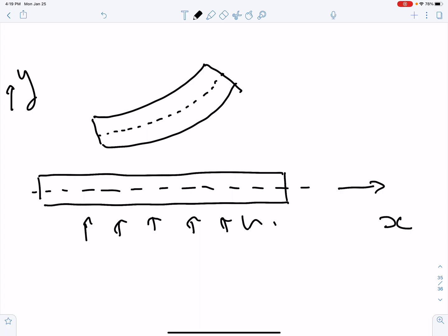Okay. So now there is some constraint on the deformation, right? So if you start by drawing a line that's perpendicular to the middle axis like this, and you put a right angle here, 90 degrees. This is a point A, this is a point B, okay? Supposedly A maps to here, B maps to there, right? And they can be connected by a straight line here. Okay? That straight line will always be perpendicular to the middle axis in the deformed configuration.